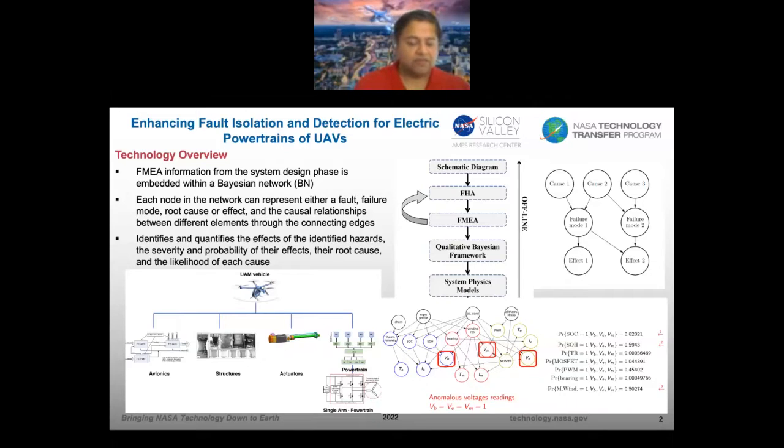causes. And that information is then fed to the prognoser. If the state of charge is the fault, the prognostic algorithm is invoked, and it can give you an estimate, based on the magnitude of the fault, of how much time is left. So is there 10 minutes before the battery would discharge completely, or do we have 20 minutes, and the pilot or the autopilot, depending on the system, needs to take a decision to land the vehicle at the safest, closest vertiport.